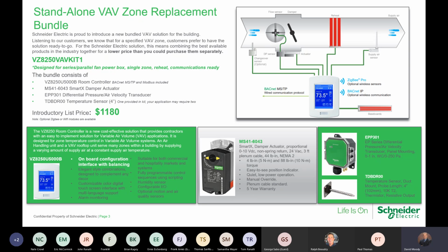Lastly, before I start asking if there's any more questions, I have taken this product that you're looking at right here and an 8650, and I've created a VVT application where the 8650 standalone does bypass damper control in all of your RTU type functionality, economizer, all of that, CO2, demand ventilation, all of that stuff, right?